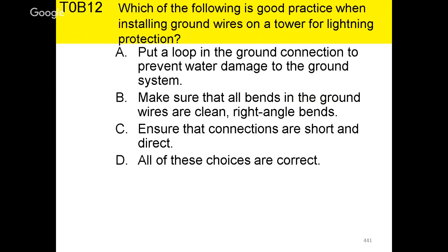Hey, Wayne. Yep, I had a little event happen here this week. City Water Authority came in and replaced my water meter. And they took out the brass water meter and replaced it with a plastic one. And then they made no provisions for bonding across the meter. I was thoroughly upset because they basically walked away and left all the copper water pipes in my house ungrounded and didn't even notify me as to the condition. Just something to be aware about. Just because it's a copper water pipe doesn't mean it's grounded. Check it. That's unfortunate. What are you going to do to remedy that?